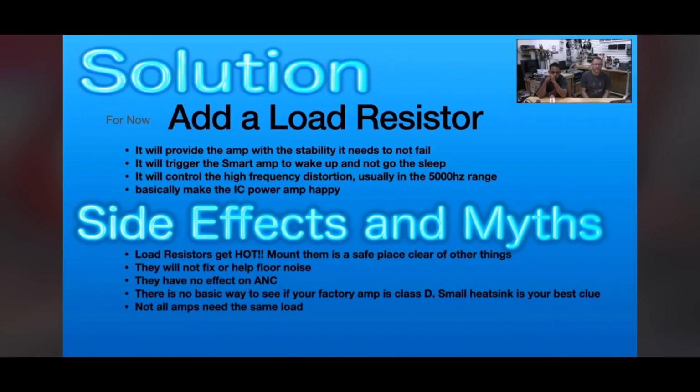They will not fix or help noise floor. This is an important thing. A lot of people think that load resistors somehow affect the noise floor in the car because of that 5,000 hertz distortion. Has nothing to do with one another. The reason you're getting that floor noise issue is because your factory system was never designed to put out the amount of signal it's needed to play it at the wattage you're playing it at.